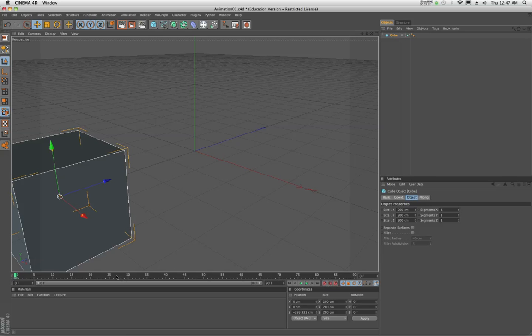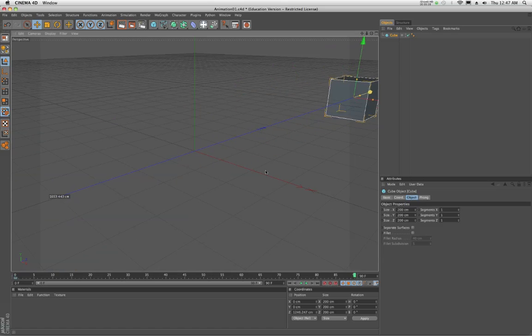The next step, and this is very important in the sequence, I need to advance my playhead to a different position in time. I can change the position of the cube, and I can record that keyframe. The minute I do that, I see an animation path pops up. We'll talk about that in further presentations, but I really have, at this point, the simple recipe for an animation.